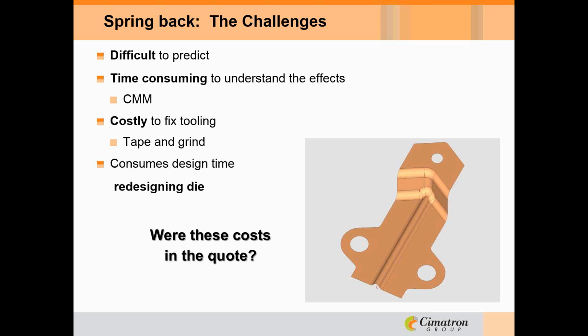Obviously, knowing that that's going to happen, typically the die maker would keep the tool soft, go through this process of grinding, taping, re-engineer it however best you can before he goes into making a hard tool. If that's the case, then that's going to consume some design time trying to redesign it and to match what that new tool is going to look like.